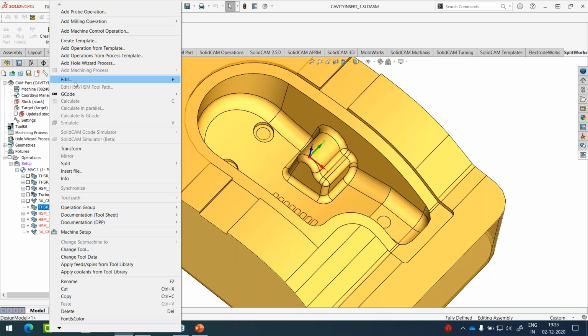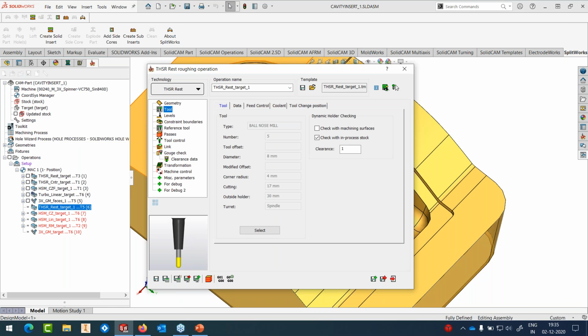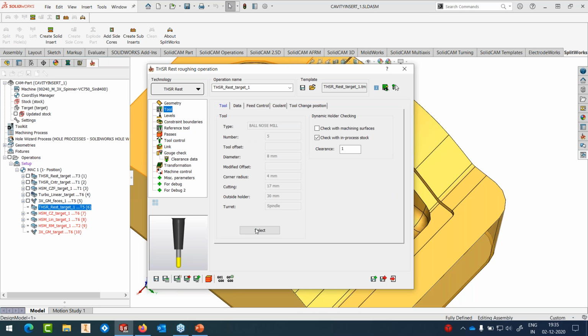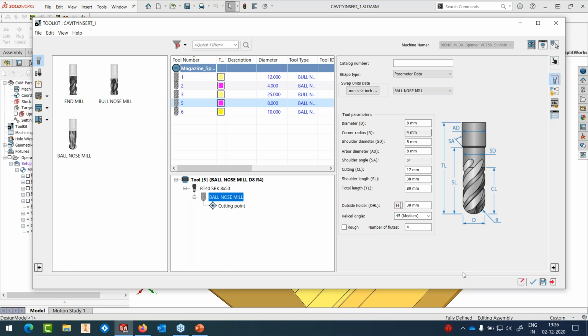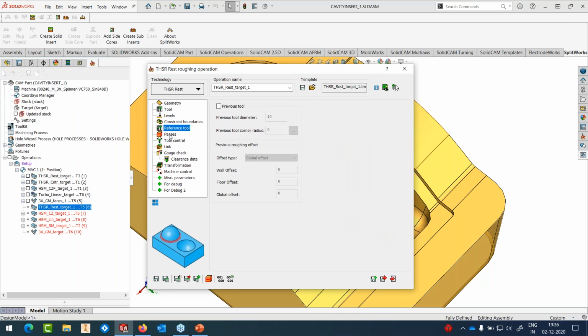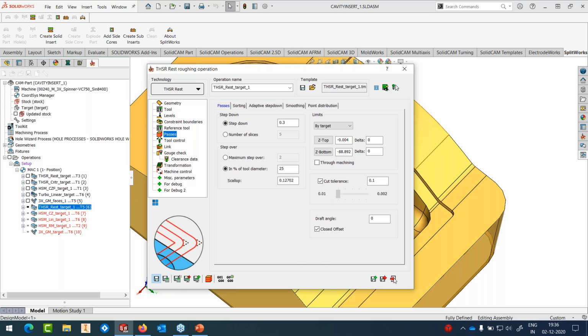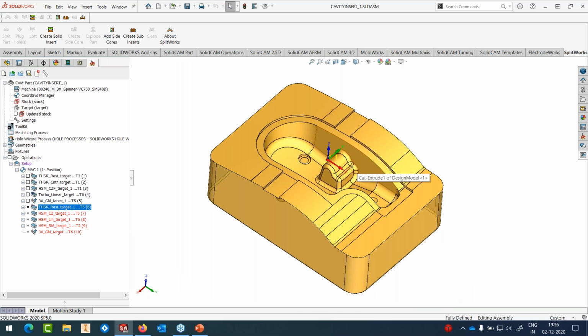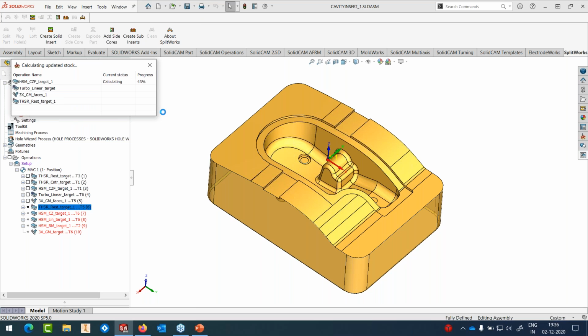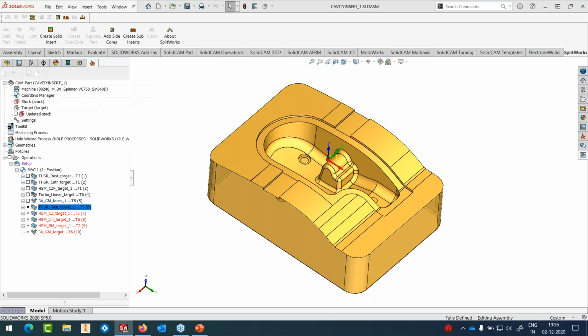Now what I will do is simply put for calculation another rest rough before I run the finishing. So take the target. The tool here is, which is this tool again here? It's an 8 diameter ball nose. No reference tool, I'm going to use the previous stock here. Remember, there are a couple of finishing operations that have already gone in, so the stock has to be recalculated for rest roughing. You can see what changes have been done in 2021, especially in terms of calculation speeds. It's running the stock calculation of the previous operation. Remember, that's 250, 175 by 70. That's the size of this part.